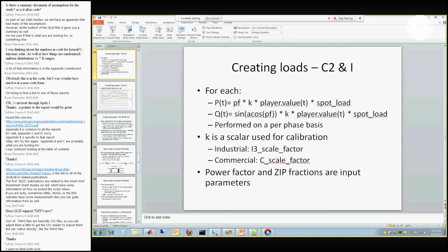Constant power or constant impedance. Yes, right. We're not messing with the currents. Okay. Kind of a secondary caveat on that: I can't remember if it's in 2.2, 2.3, or which version we put it in, but there was something added to the load objects where you could specify it kind of like the IEEE taxonomy or the prototypical feeders, where you specify just the power of the constant current load and then give it the power factor, and inside GridLab it'll handle all the angle offsets.